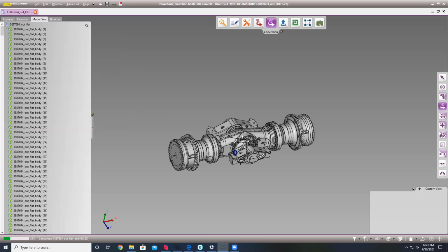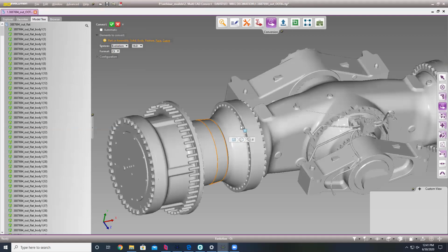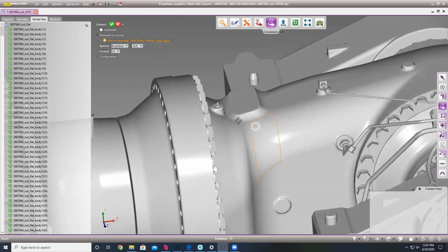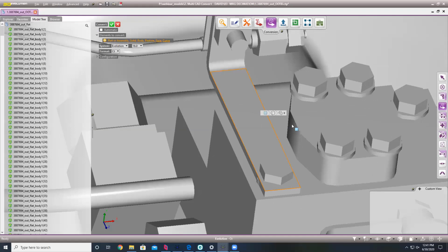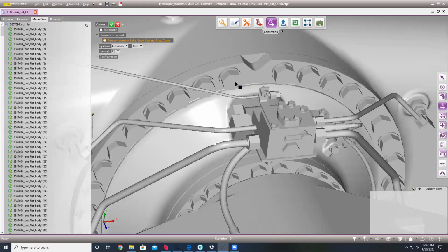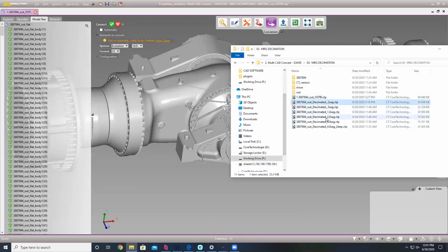And then save the file. It's actually already pre-saved, and I calculated a number of different values for that sag. Just so you see how the geometry has been simplified, but it really looks exactly like it did before. There has been no real degradation in quality, other than the file has been decimated. So when you look at the size using 2 millimeter sag, you can compare that it went from 90 to 19 megabytes. That's almost an 80% reduction without even doing anything except for file save.